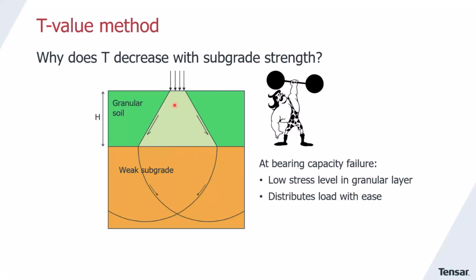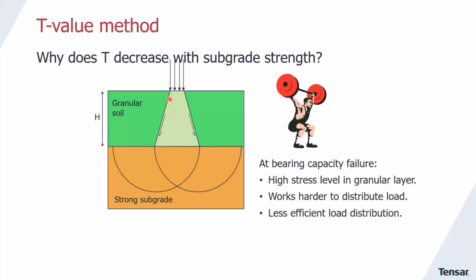The transfer efficiency is very efficient, and we can have a very optimal transfer of loads through the stones, because the stones don't have to work that hard. On the other side, if the load is very high or the subsoil very weak, our transfer efficiency decreases, because the stones have to work very, very hard to get all the stresses transferred through the stones. In an analogy with this gentleman who has to strain all his muscles and is less efficient in holding the heavy load.